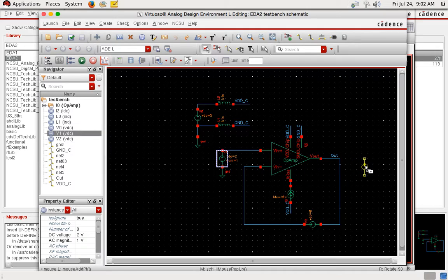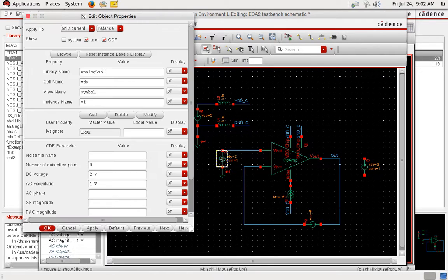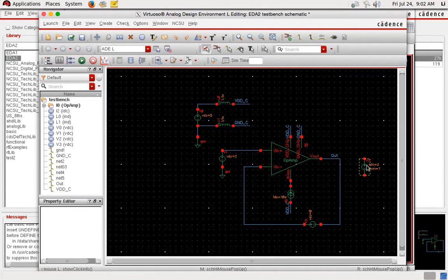What I do is I can actually place an AC voltage source here, right? And I can disable the AC information from the input side. Now I'm gonna test what's gonna be the impact if I have AC voltage at the output side, right? But the tricky part is I can't make a direct connection from here to there, because if I do this, then the DC voltage of this guy is gonna mess up with your operating point.